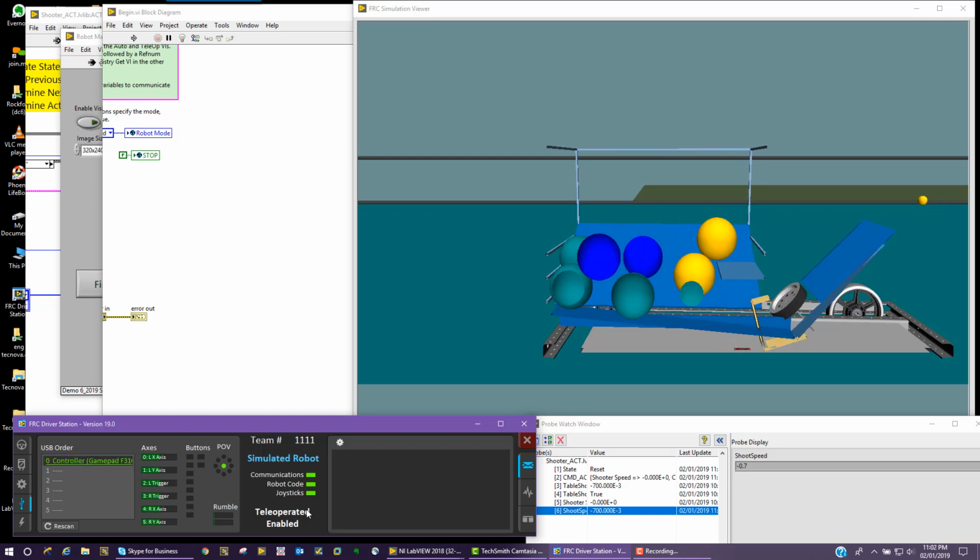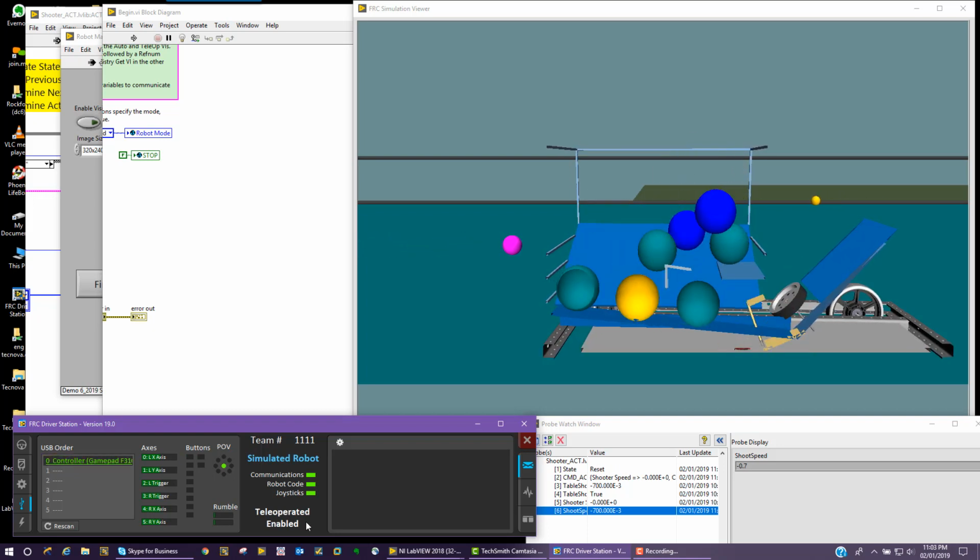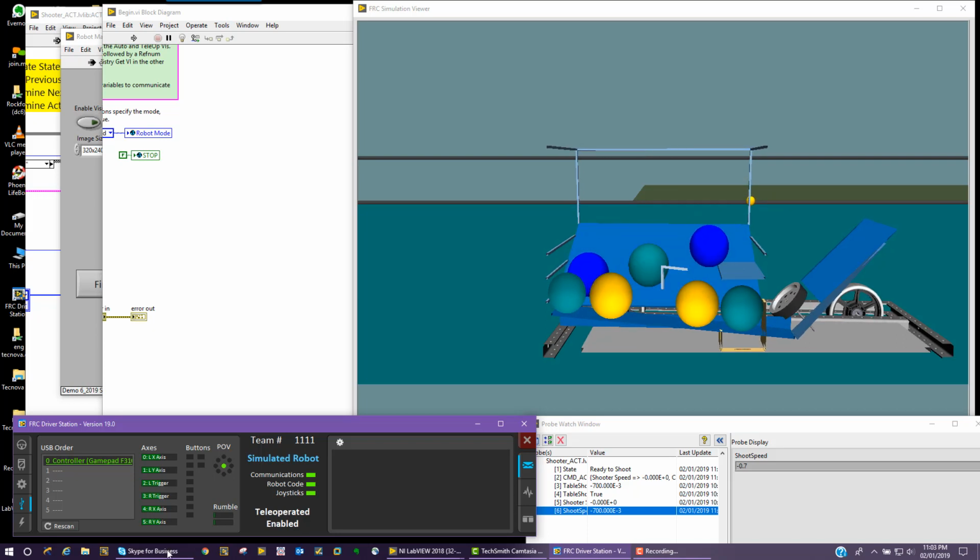It doesn't matter how many times I push the button, it will only go once and return after 2. So it gives us timing and stability. Doesn't matter how fast I push the button, it goes a half second forward and 2 seconds back. And I think I would probably extend that to maybe 3 seconds because it's still got to have time for a ball to roll into the shooter.